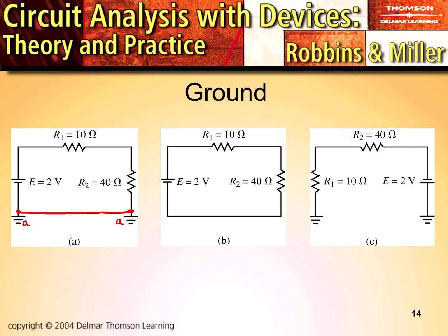But what you do need to understand is that when making voltage measurements referencing ground, with a B here and a C here, a single subscript voltage like VC or VB means the other point of measurement left out is ground.